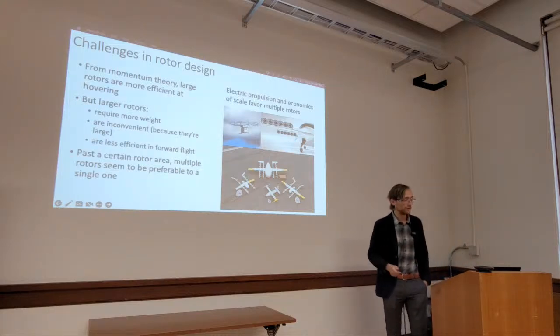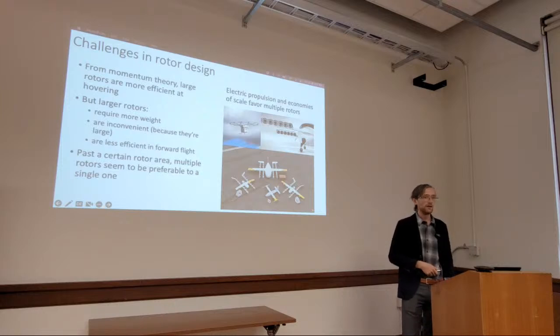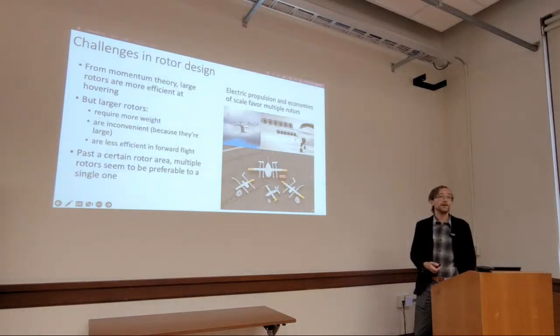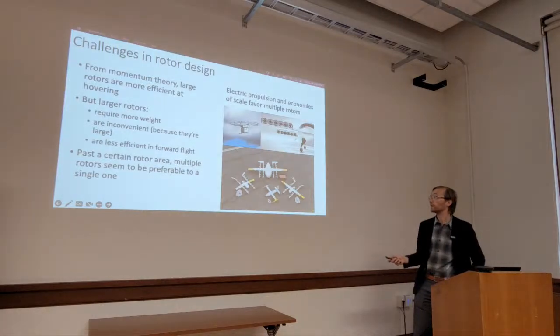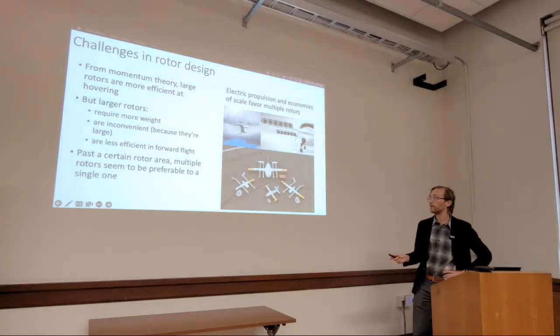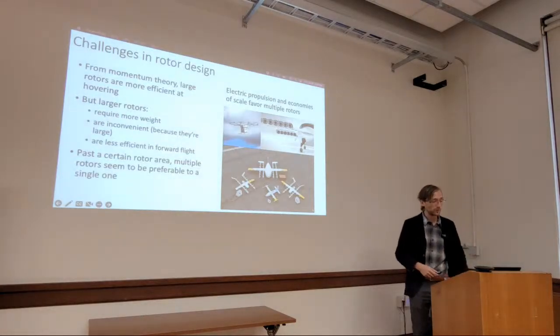And there are other obvious advantages, which are redundancy and lower noise. And also, I'd like to mention an important one, I think, which is the economies of scale by having many small rotors perhaps used on different types of vehicle rather than each vehicle having its own rotor. And you can see on these, well, there are actually two different prototypes here, by Wingcopter, they have the same rotors, same propellers, so the exact same components for the propulsion. The only thing that changes is how many of them there are to adapt to a given payload weight.